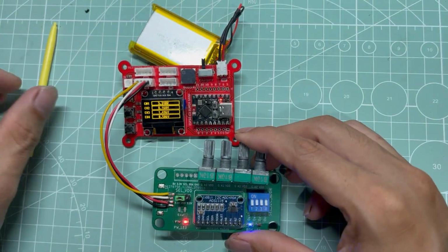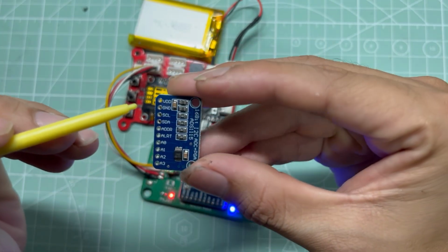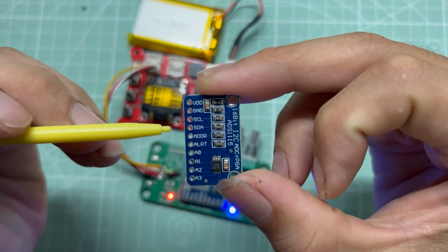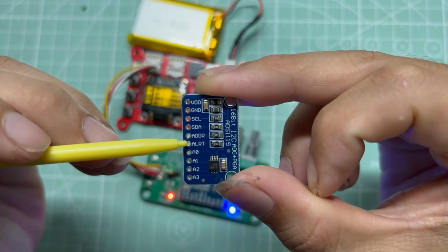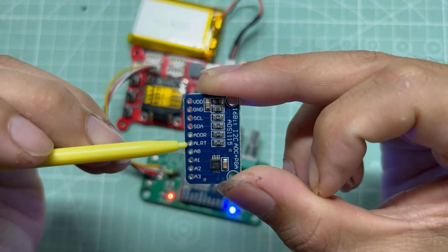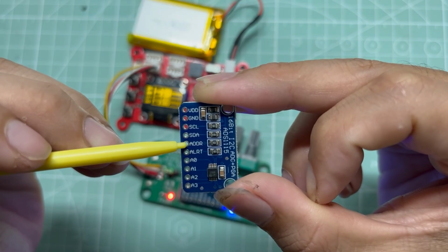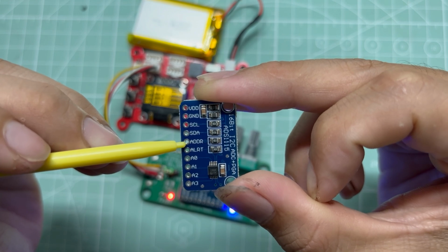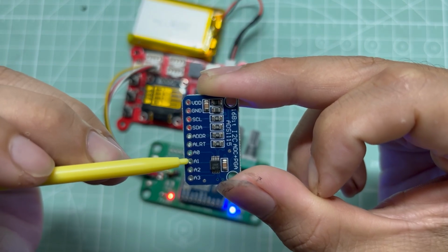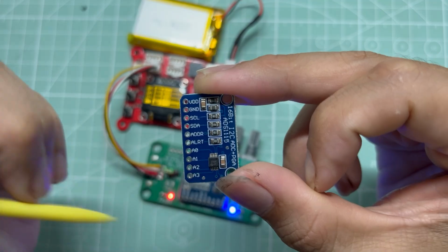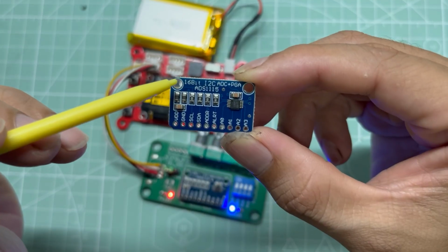So, let's get started. This is a 16-bit ADS1115 module that I bought from AliExpress for a pretty low price. The module communicates through the I2C interface, which makes wiring and integration quite simple. You can select the I2C address using the ADDR pin, allowing up to 4 different I2C addresses. This means you can connect up to 4 ADS1115 modules on the same I2C bus if you need more analog inputs. Each module provides 4 16-bit ADC input channels, labeled A0 through A3, which can be used to measure analog signals from a variety of sensors and devices.